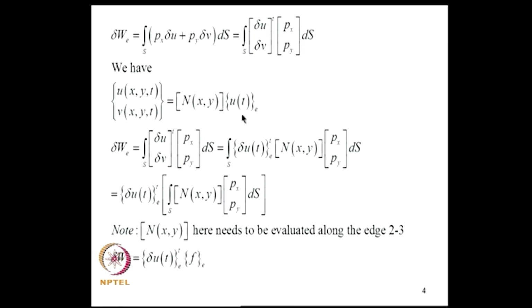The virtual work is also equal to virtual nodal displacements into these forces, and after we manipulate this we get this expression, and we should note that these trial functions need to be evaluated along the edge 2, 3.